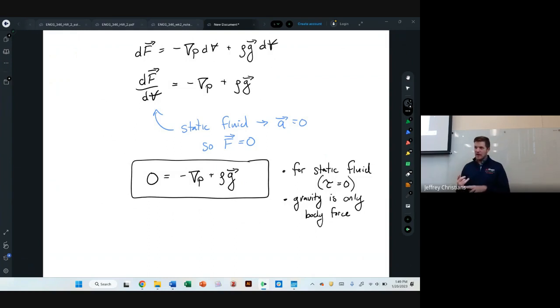If I were you and didn't remember anything that I learned in computing, not that that's you, here's a tip. I think how you're going to make the plot is the MATLAB function quiver. That's going to make the vectors. So how you're going to solve the problem is you're going to go to MATLAB, go to the command help, and type in quiver and find the help function for that to be able to remember how to do that.